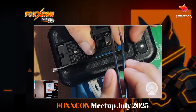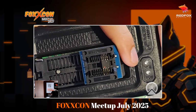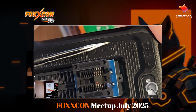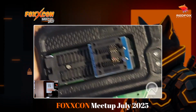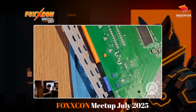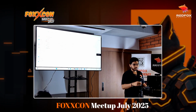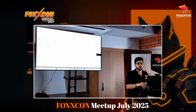Yep, that's connected. You see, the chip is connected, and as I mentioned, this dot you see out here should map to this dot. Yeah, you see that dot right there? That is also where the chip reader starts. Alright. Now, moving on to the practical itself. Now, to run this specific reader, you need software called XG Pro. It's software for this specific brand of reader. If you have a different brand, then they'll probably have a different reader software of their own.